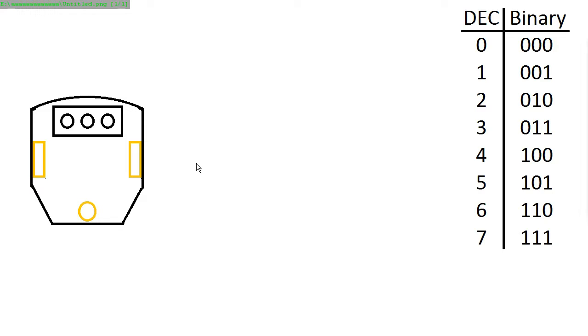The way I approached the problem was to look at the line sensor and all the possible combinations of sensing that can happen. So in this particular instance, we can have this sensor detecting a line, or we can have the middle sensor detecting a line, or this sensor detecting a line, and even the line crossing two sensors.